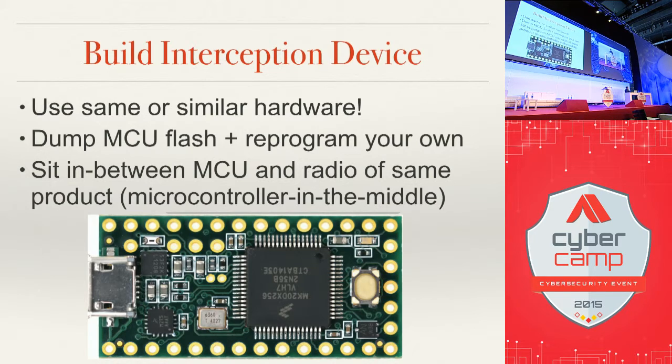Sometimes I'll intercept a chip, so I'll actually cut a pin and then tie it to my device and then tie that back to the actual chip. That way I can do on-the-fly man-in-the-middle attacks on the communication between my circuit and the car, for example.